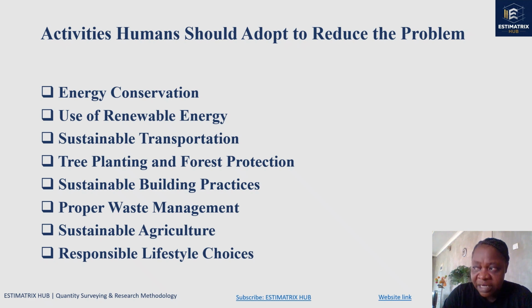And then we can make use of sustainable building practices. Use environmentally friendly building materials, like I mentioned, wood and glass, instead of using cement and blocks, which emit so much energy to produce in all these big industries. Then we design buildings for natural lighting and ventilation. We can design our buildings for natural lighting instead of using all these things. We increase the size of our windows, and we have a good design that can bring about that. Then reduce cement usage where alternatives exist.